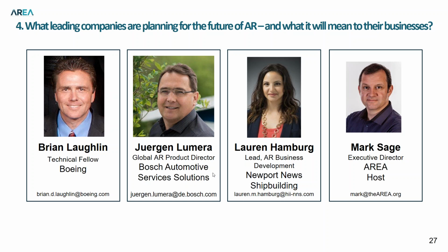Sure. So that's a really good question. For example, if we take the CATIA drawings, CATIA drawings are very large. They are massive files. And so how do you put that on a HoloLens when a HoloLens can handle upwards of possibly 5 million polys? We find that 2 million or less is where it's happiest. You get too many polys and it starts getting jittery and you have all kinds of anomalies that are not conducive to what you're trying to do. So we actually have a decimation process that we go through, and that's been a really big part of our journey using AR, specifically with HoloLens: how do you find that happy medium? What is enough in terms of resolution on a particular image?